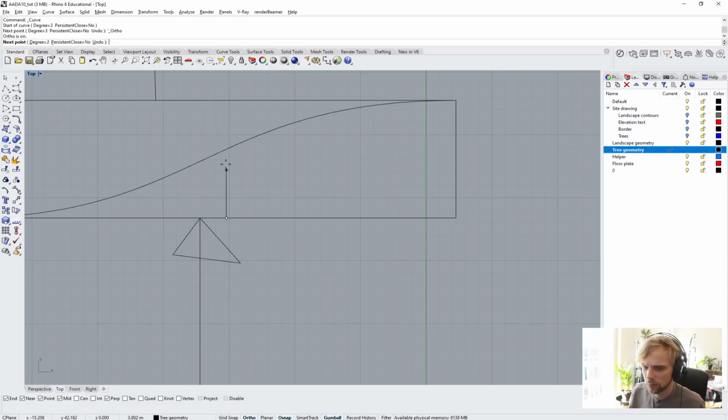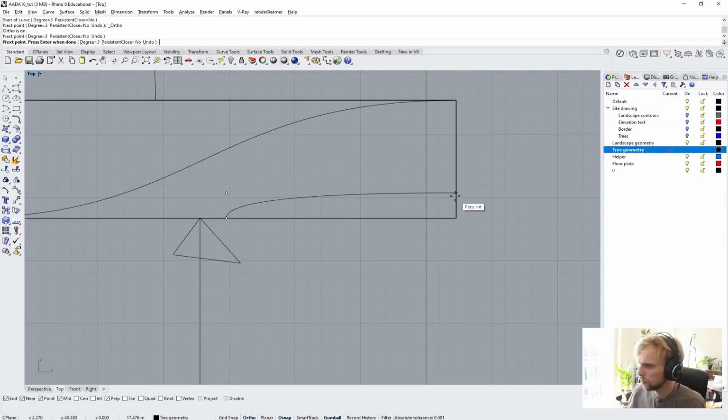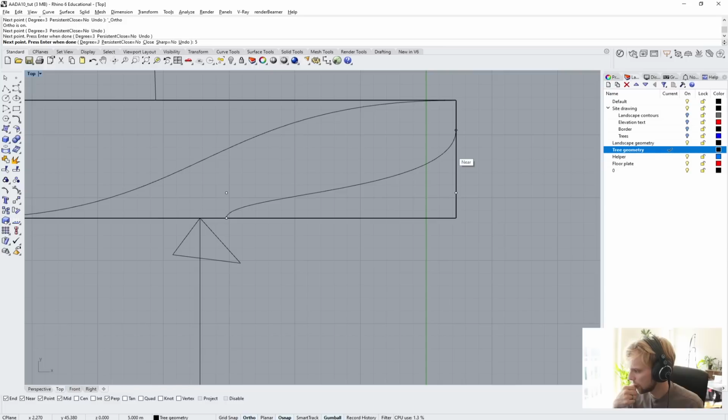And then I'll maybe use F8 to snap it to the vertical direction. Let's say 2 meters up, then snap to perpendicular here, and then maybe 5 meters up again. No, 5 is a bit too... So here I'm working with proportion, right?